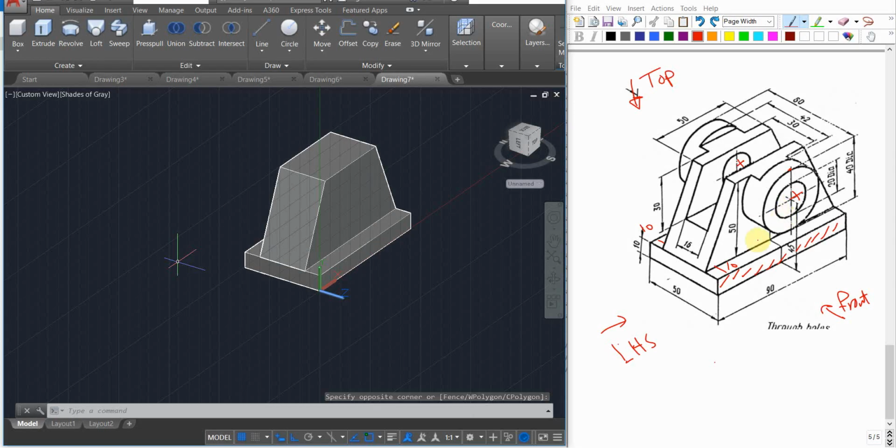So this is what we're gonna do. One of the simplest things is just to draw a circle over this face, with a diameter of 40, but its center point should be from the midpoint. This is the midpoint of that line. You're gonna go up with 45, right? You're gonna go up 45 to locate the center point over this face, then you're gonna draw the circle. Okay, so this is one of the approaches. Or you can draw the circle over the front of you and move it back in the middle to be located in the middle of the shape.